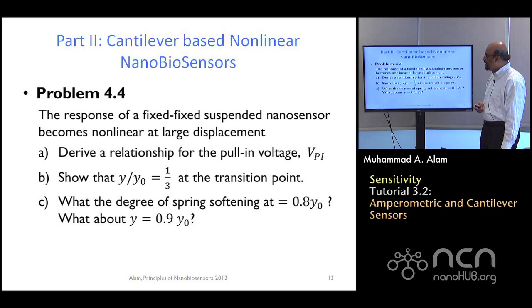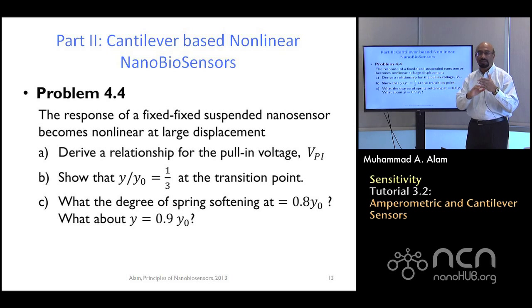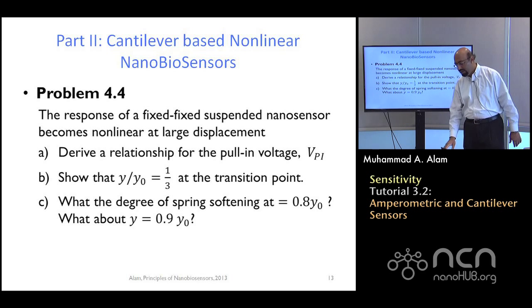Now, one final thing I wanted to mention about this cantilever-based biosensor is that there is this new version, right? It's called a FlexureFET. And the FlexureFET essentially combines the biosensing associated with the simple cantilever and puts an electrostatics interaction so that the cantilever bends to a point where its sensitivity is much higher.